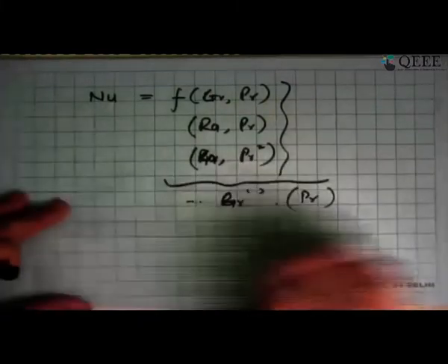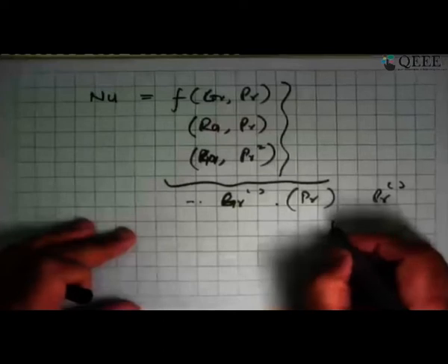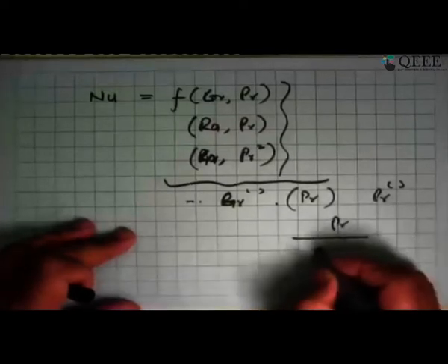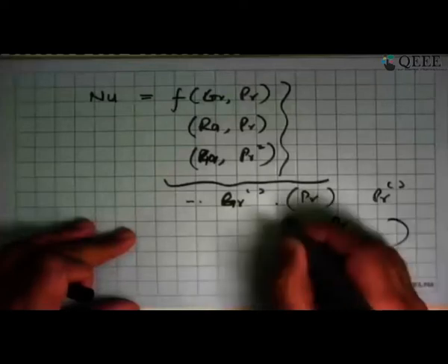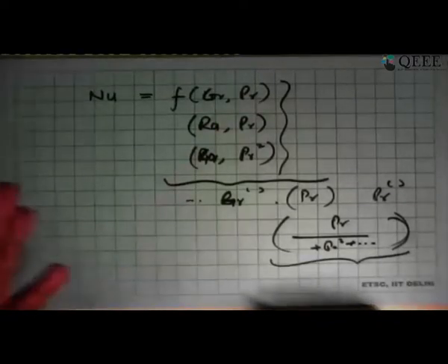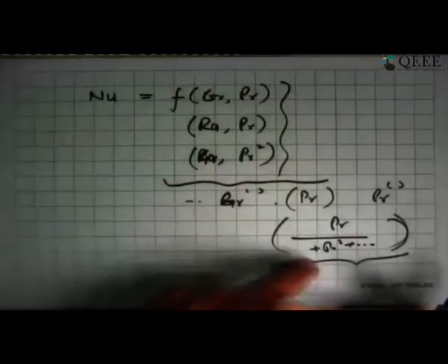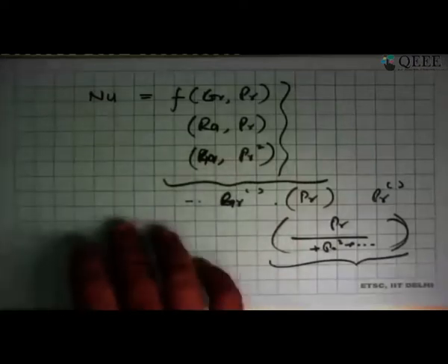If you look at forced convection, the Prandtl number was raised to some power, and that was the answer. Here it will be Prandtl number upon something into Prandtl squared plus something, something, something, and these equations become a little bit longish and complicated. Essentially, they are nothing but a way to express the dependence of the problem solution on the Prandtl number. Okay, so that's what we have.